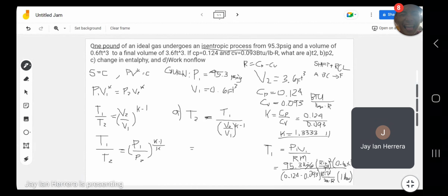By unit analysis, we need to multiply the denominator by BTU per pound force to cancel BTU, that is multiplied by 778 foot-pound force per 1 BTU.